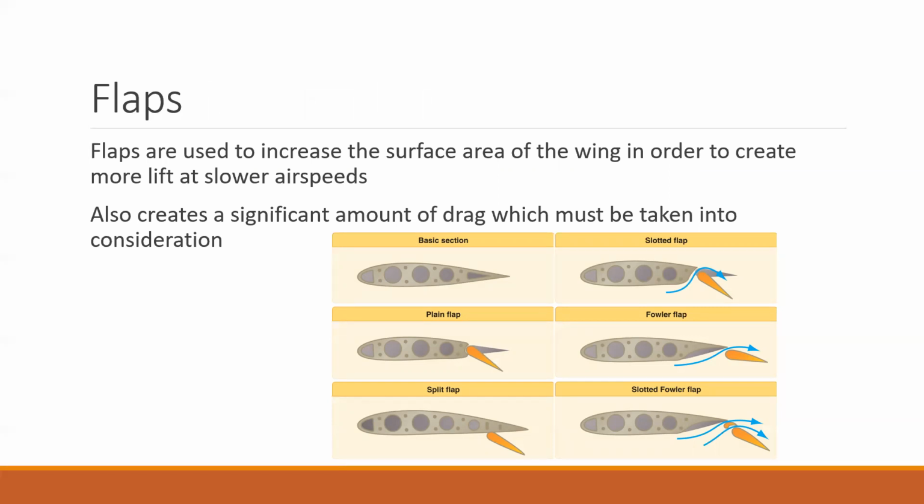And so there's a lot of different types of flaps. There's just none. You could just have no flaps. You could have a plain flap, like as shown here in this diagram. And the plain flap just kind of rotates around this center axis here. And it doesn't really do much. It just kind of goes up and down. I've never really seen an aircraft that has these, but they're out there. Kit-built aircraft probably, or some other simpler designs, because this does not incorporate any other moving parts. It just rotates.